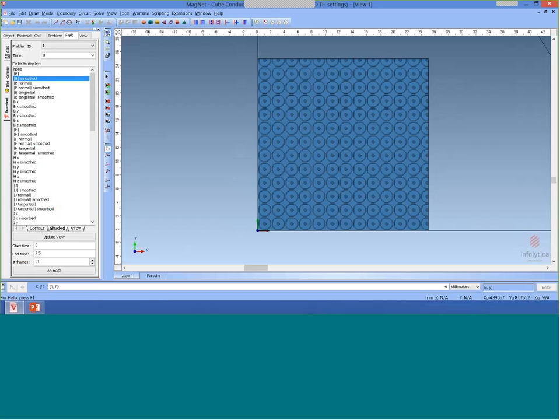One of the things to note is that when you use the surface impedance, you don't actually get the field distribution inside the volume. But we also have features that let us model the inside in a more efficient way, and one of those features is using mesh layers.